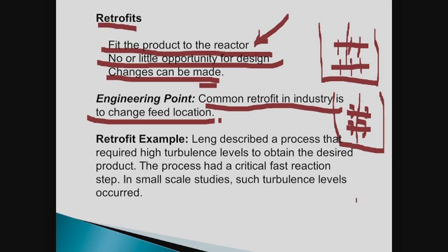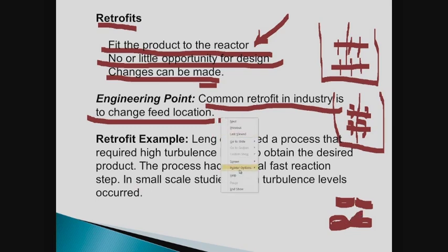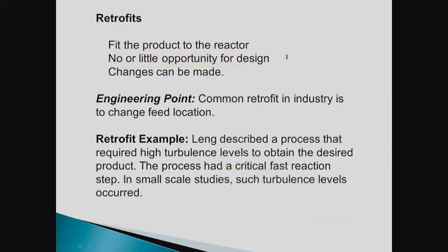Or if you have a pitch blade turbine for overall mixing, you replace it with a hydrofoil. A hydrofoil saves you a lot of money in pumping costs. So retrofits are common in industry. And changing the impeller is quite easy. It's not that hard, usually.